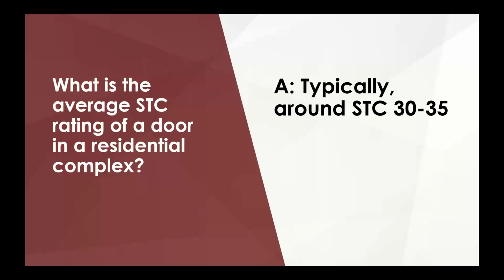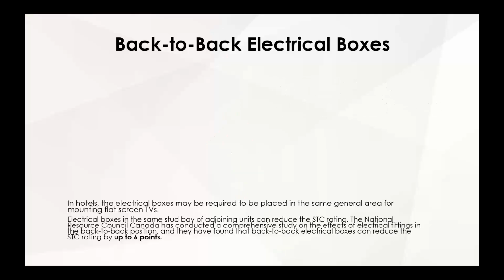So if you ever run into that situation, remind the consultant that, hey, when I get down to the door, the STC is going down anyway. So it doesn't matter if I use a 20 gauge stud there.